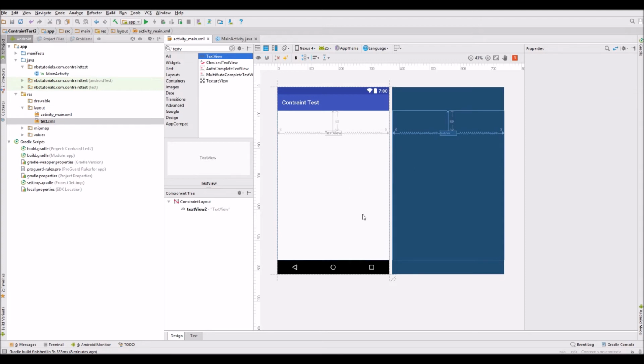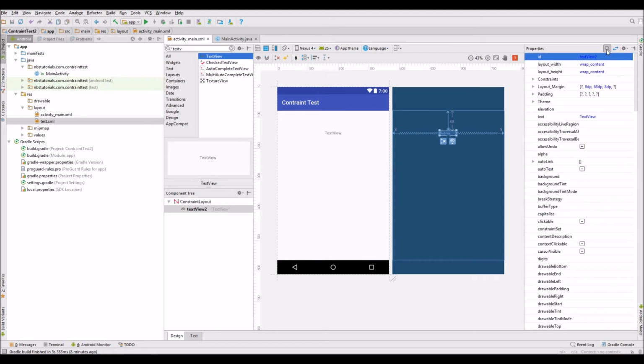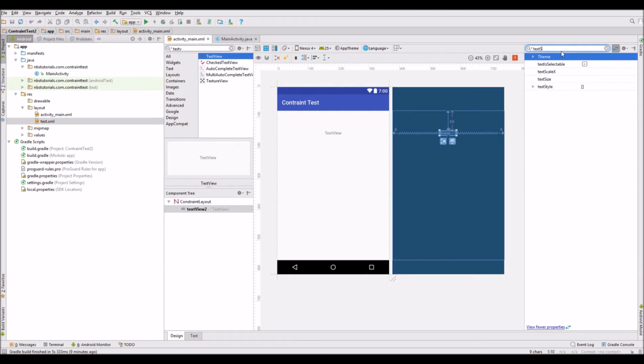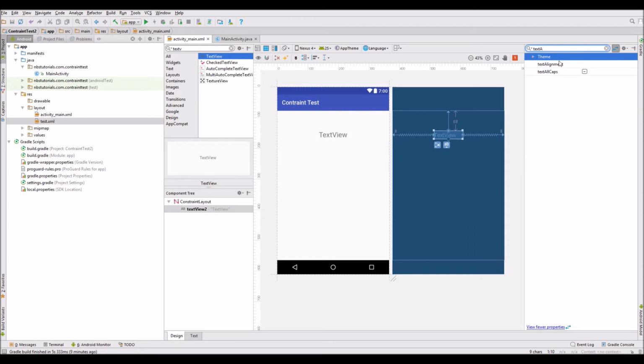So what I'll do now, I'm going to change the height of this text. So I'm going to change some of the properties of the text itself. I need to find that particular property. So what I can do there is bring the properties up with that switch. Same button is here. I'm going to search for text size. That's what I'm interested in. I've got some predefined values in here. It's a title, so let's make it fairly big. I really want that aligned in the center as well. So if it's text, I can find text alignment, and I can just center that text.